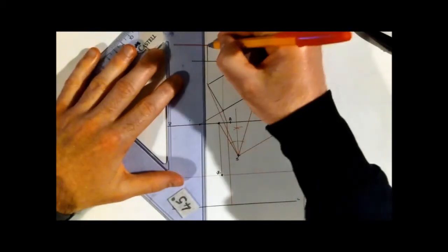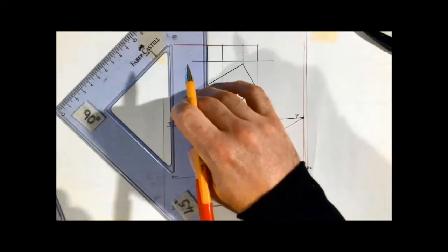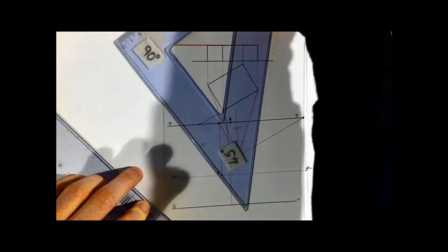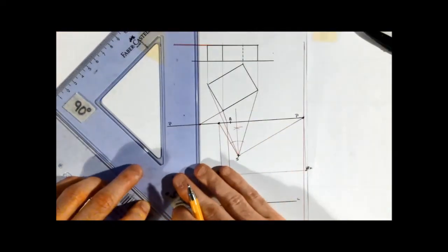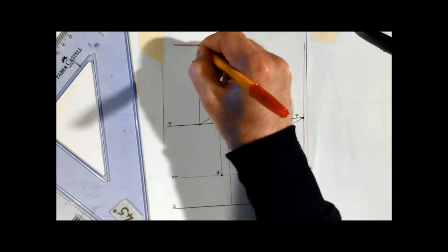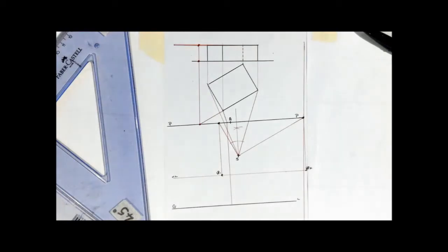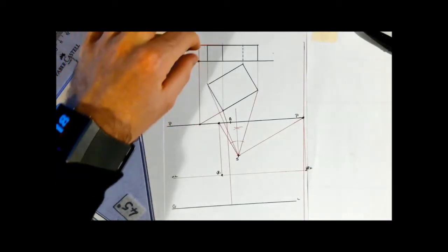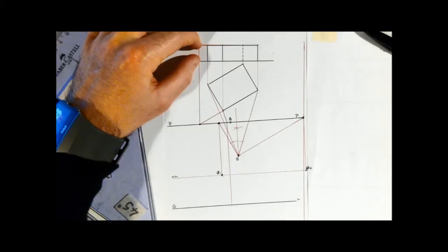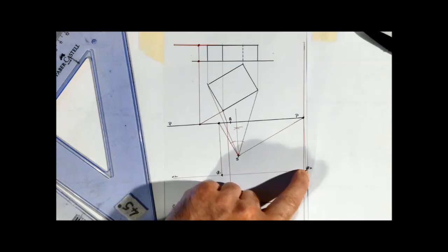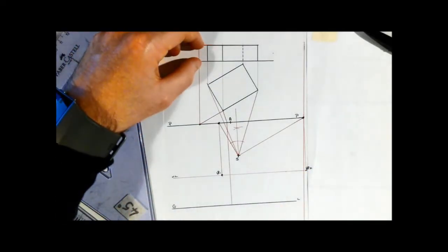Okay? And at this point then, where it's hitting our picture plane, technically in elevation, at this point here and here is where it's hitting our picture plane. Okay, you have to try and imagine that. It's hard to visualize, but that is where it's hitting our picture plane. So what we're going to do is, at that point there, I can take it as a true height. Okay, and then vanish it back in this direction, which is going to VP2, like we did in the previous question. It's only at this point I can take it as a true height.